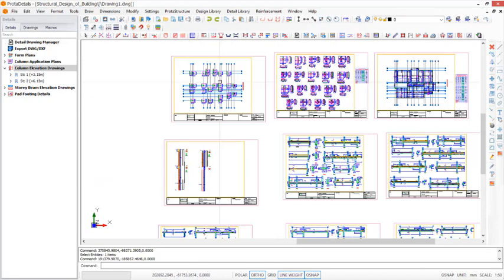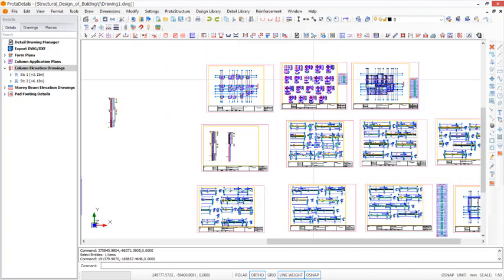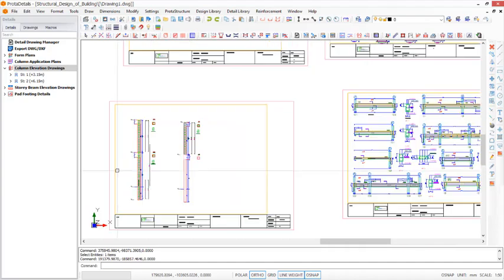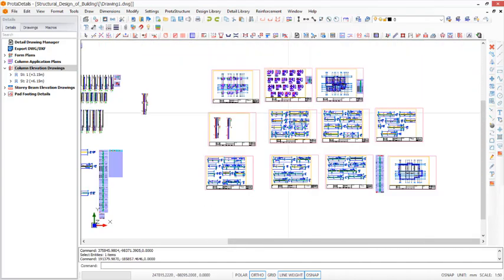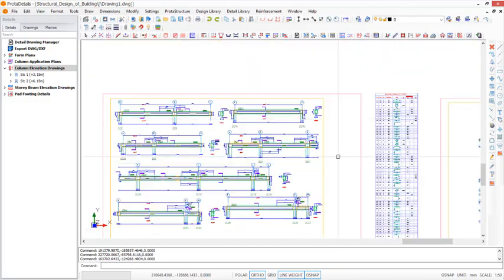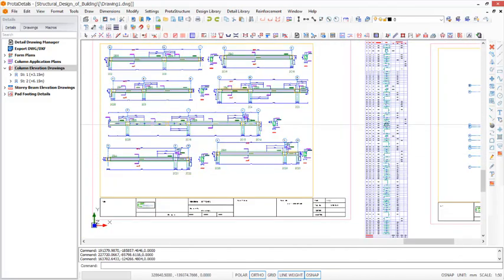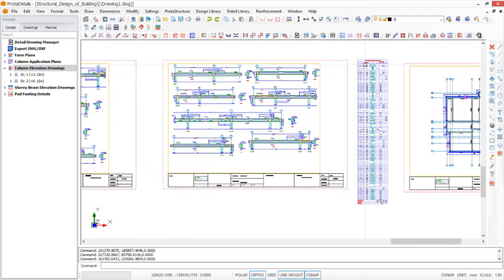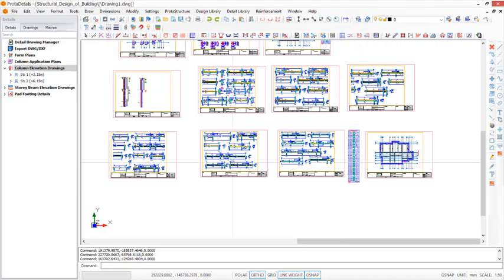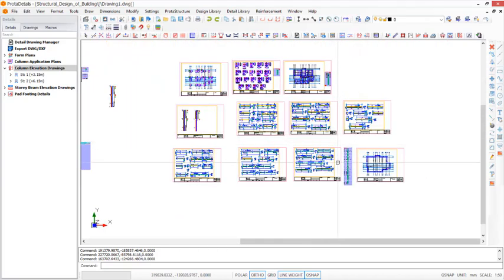Okay, if you zoom closely, you will notice I have the foundations, I have the columns, the raft footings, the slab details, and the columns right there. Then the whole of this is the first floor beam, and this is the roof beam, and then beside it you have the bar bending schedule. All right, so this provision you have there is basically meant for this bar bending schedule, but in this case this is quite longer than the provision right there. Okay, so that can also be adjusted.